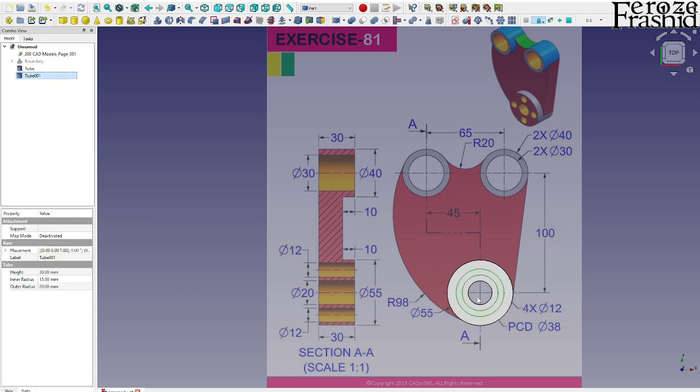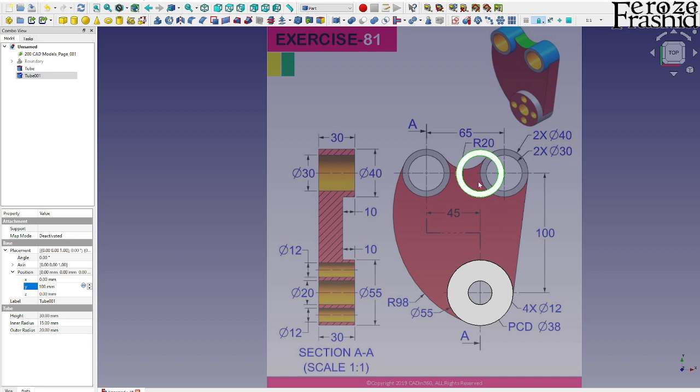We got this one here, and I have to move that up there, so we can do that from here. In this placement position, we know that in the y direction it goes 100 millimeter above, and in the horizontal direction it will come to this point, which is 45 millimeter on the negative side on the x side, so minus 45 there. So we placed that one there.